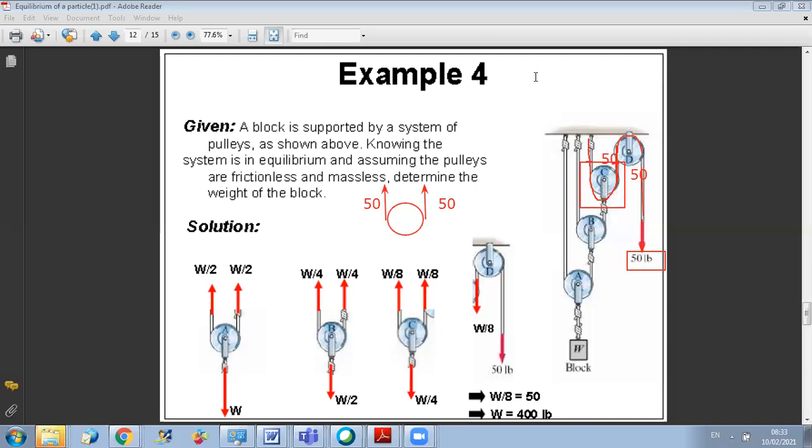Yes, because look, it's the same cable here. Follow the cables. Here we started by this cable from this point. This cable is going up, it's going over the first pulley. Okay, it doesn't end yet. It's continuing down. I am moving with it. It's turning over C. The end of this cable is here at the ceiling.